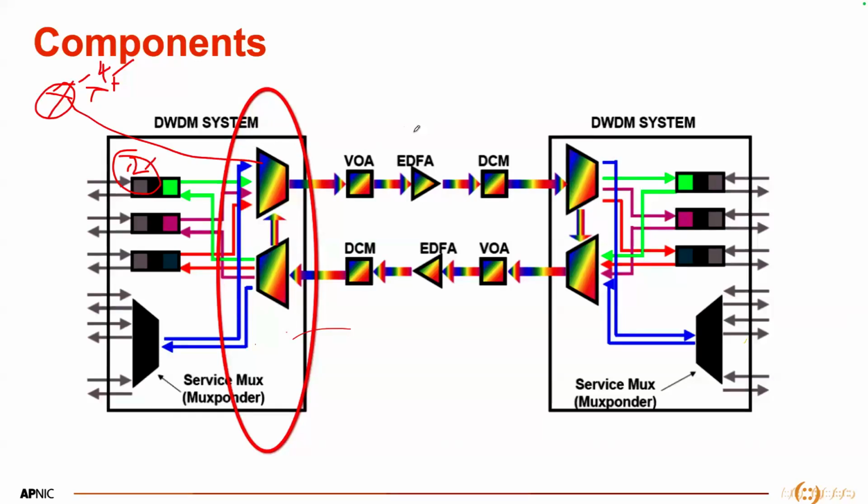Maybe in the EDFA you have applied 12 dB gain, and this 12 dB has come from a detailed calculation where the TX launch power for the OTU is minus 2. Now, if you connect something with minus 4, it will pass through the same EDFA with 12 gain. So at the receiving end, it will show a weaker signal compared to your own native lambdas. Are you getting my point?